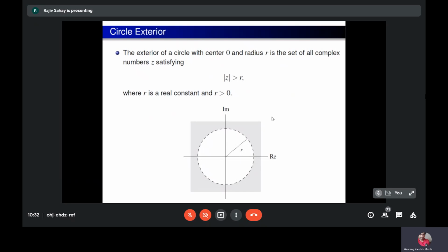Okay, so whenever you are given the Z transform expression, you want to find out the inverse Z transform and go to the time domain and want to see how x of n looks. So you cannot do it unless you are given the ROC. So we have to be careful in the Z transform. We were not talking about the ROC in the DTFT. Okay? So here we are talking about the ROC.